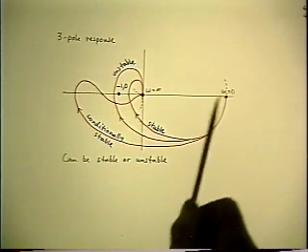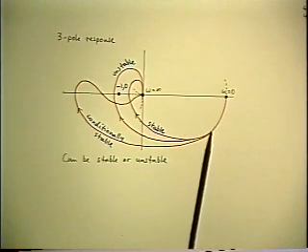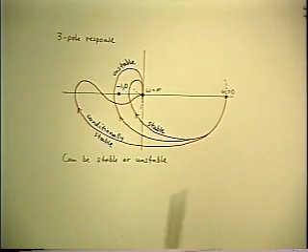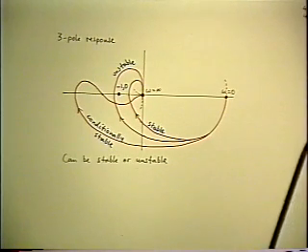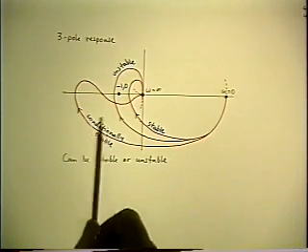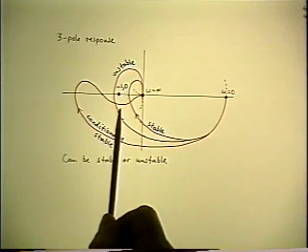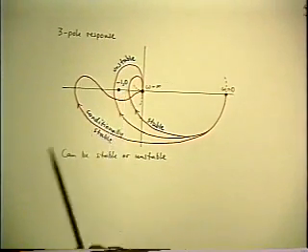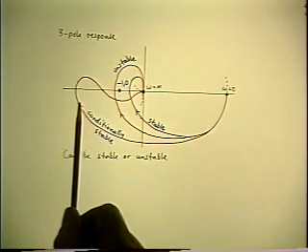There's no point in looking at four poles or higher, because obviously there's just more variables involved, and you have the same conclusion. It could be stable or unstable depending on the numbers. But there is a third contour here, which is a sort of pathological one. According to Nyquist, it's stable, because it doesn't go around the -1 point, but it has the peculiar property that